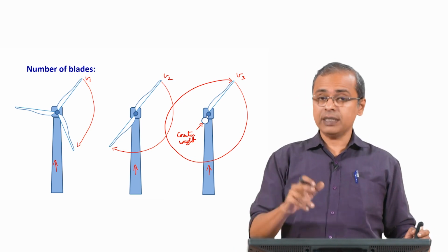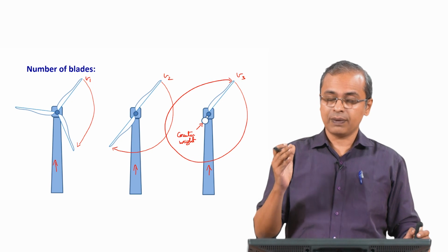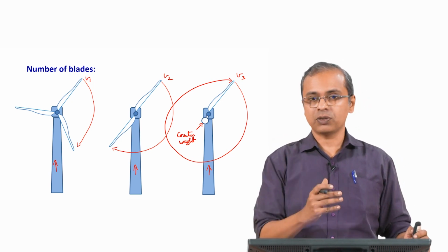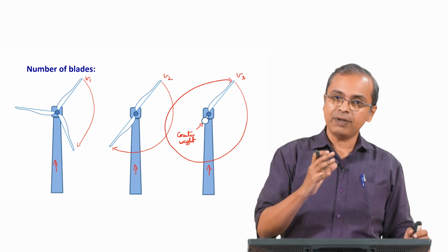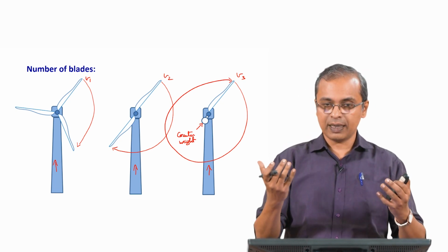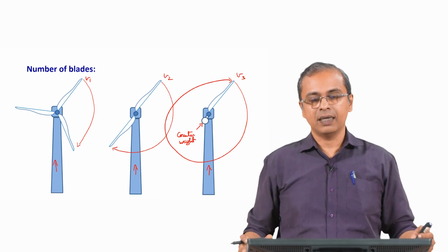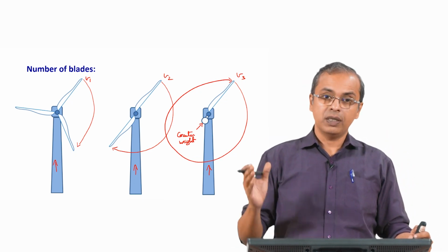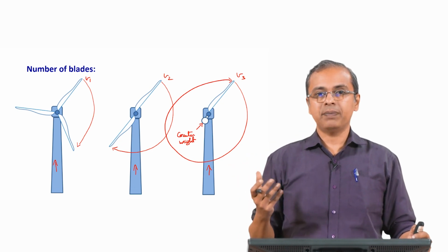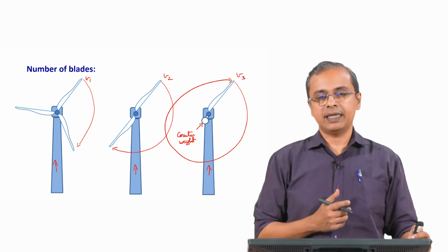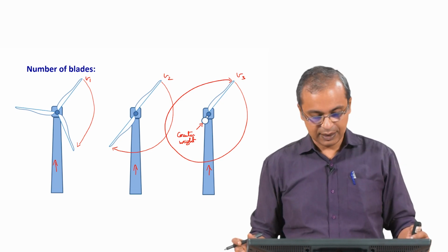And like I said, if torque is important, where you do not mind the speed of the windmill, but you are more interested in torque. So, RPM is not important, but torque is important. Then having more blades is useful because you are able to get more energy from the wind that is going through that process and then use that to generate that torque. So, the older design windmills which were primarily aimed at grinding things or pumping up water, where torque was a critical thing, they typically have more blades that are put up.